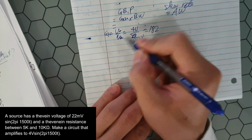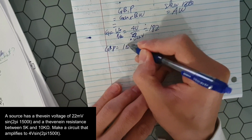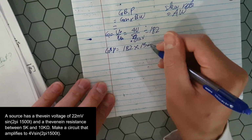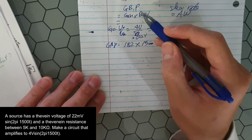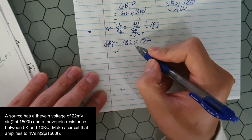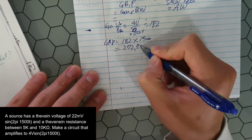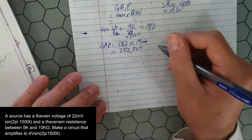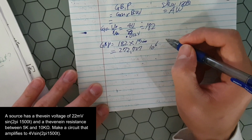For the gain bandwidth product, we will do gain times bandwidth. So 182 times 1500 hertz. Make sure that the bandwidth is in hertz for GBP. And if you do that, you should get 272,727. And the typical op-amp has 10 to the power of 6 for its gain bandwidth product.